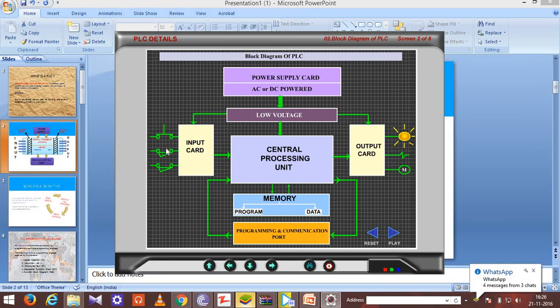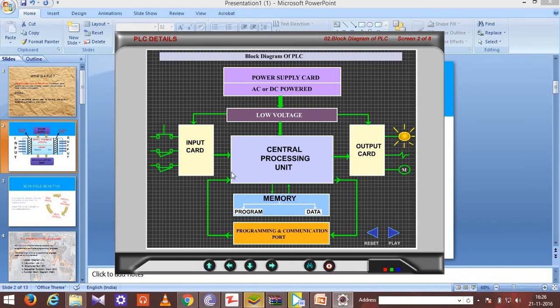Now if you press the button, an electrical signal will be sent to the PLC, and the PLC input will deliver this to the CPU in a format understandable by it. The CPU will process the data received and send the result to the output card, and the output turns the data to a raw electrical signal again and supplies to the lamp, so it turns on.